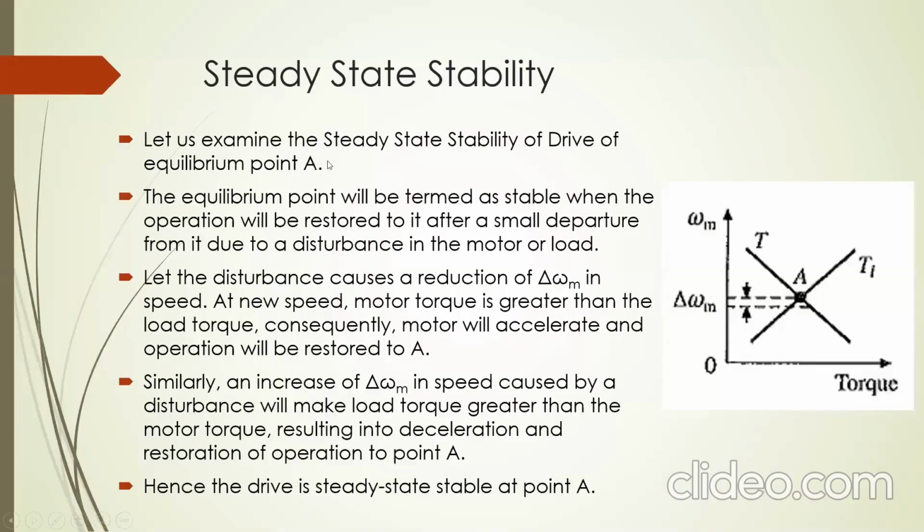Okay, let us examine the steady state stability of the drive at equilibrium point A. The equilibrium point will be termed as stable when the operation will be restored to it after a small departure from it due to disturbance in the motor or load.